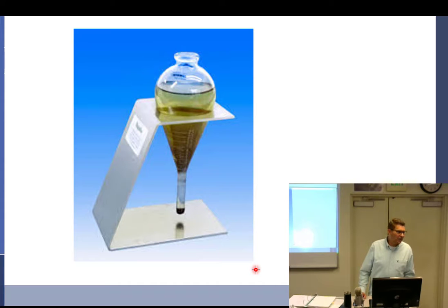Just take a rag and start wiping it. I actually use the fluid and wipe it all down to get rid of the buildup in the machine. You'd be surprised how much the concentration goes way up, so you have to be careful with that. But you've got to check it every day. And you want to check it for at least an hour, letting it settle out in a vibration-free environment.